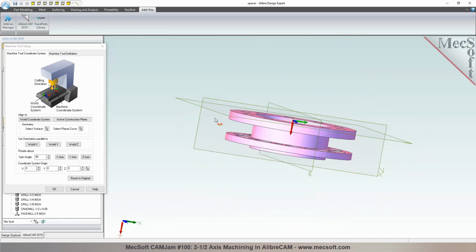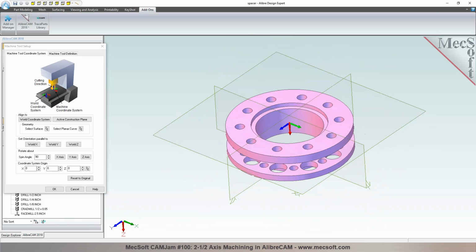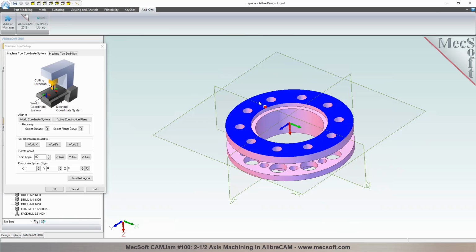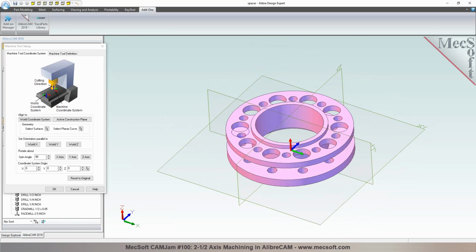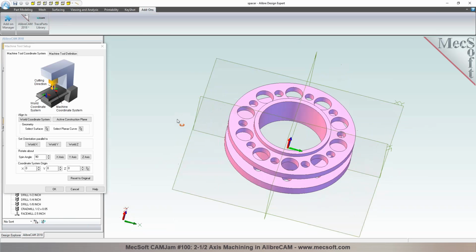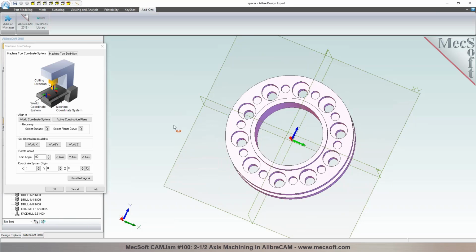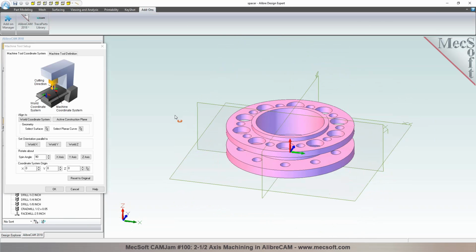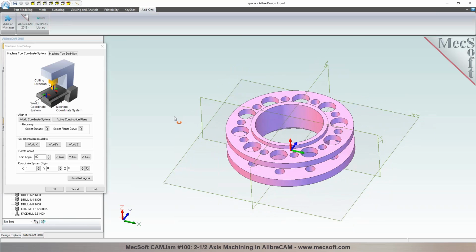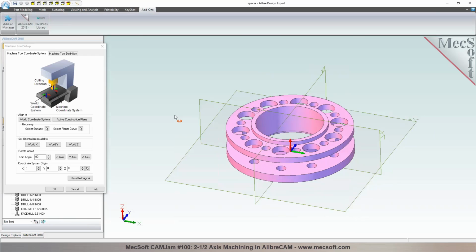Okay? Now, this particular part, would you like to program from the back side first, or would you like to program the top side? I would do the top side, and what I had interest in is if we could program the boring of the holes, and then it's got that shoulder there. Like if the material was full thickness of the highest point there, mill the shoulder back. Okay, sure, we can certainly do that.